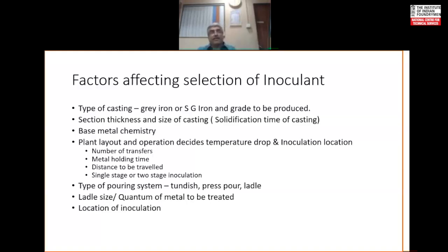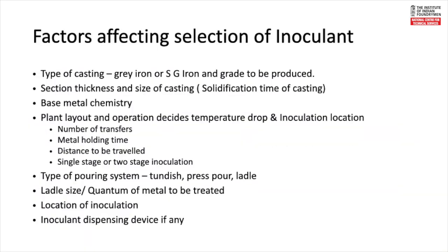These are all the factors which will then decide what is the chemistry of the inoculant that you will choose, what is the size grading of the inoculant that you will use, and at what location and in what manner you will add inoculant into the ladle.